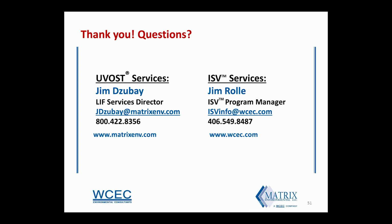They're both going to cause you the same problems. And the percent RE can be a misleading way to look at it if you're looking at an absolute percent RE. So the important thing to remember is that if you detect it with the LIF, it is LNAPL. And that LNAPL is going to keep that site open for years to come if you don't deal with it directly.